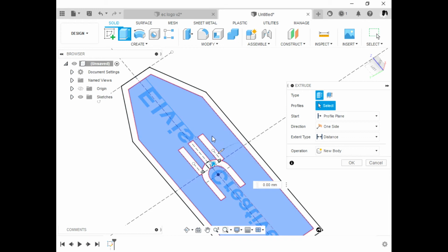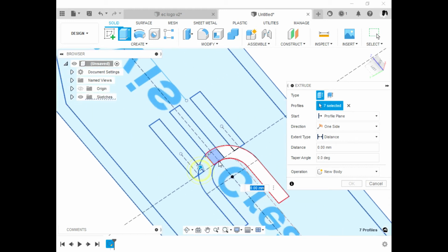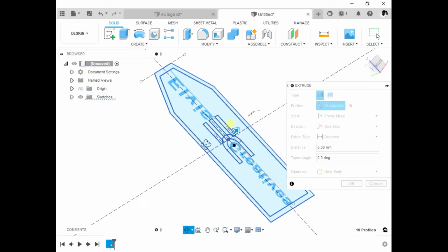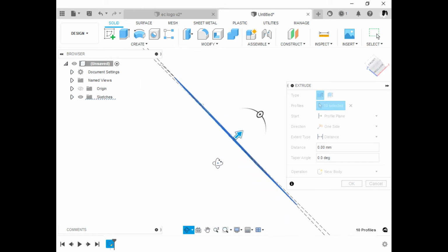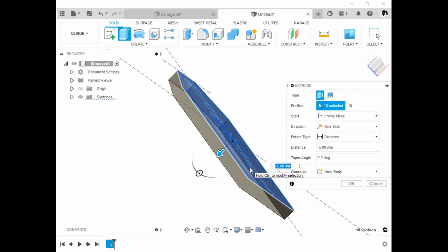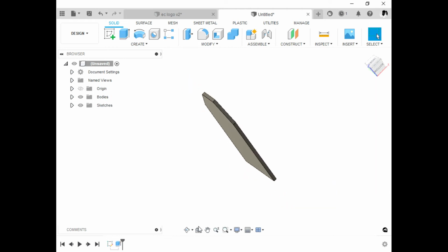The first one will be in the opposite direction, and it will be completely flat, while the other one will try to show the writings and the logo. The flat side will be on the print bed, because with a 3D printer we don't want those rough edges as a result of supports. We want a smooth looking thing.